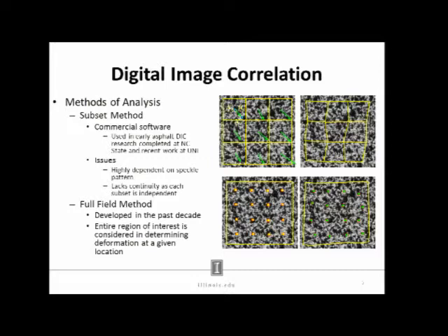And in general, with this region of interest, now you're not seeing these little elements in between each one. Now you're specifically looking at points such that there's a given constraint saying that we need to make sure that we have good continuity between each point so that we don't have large jumps in displacement. Because really the only time you should see large jumps in displacement is at a discontinuity where you're driving a crack through your region of interest.